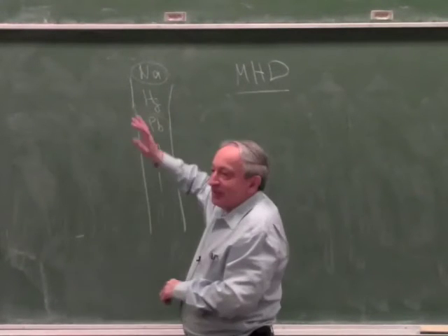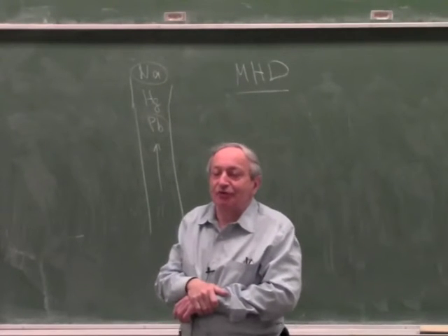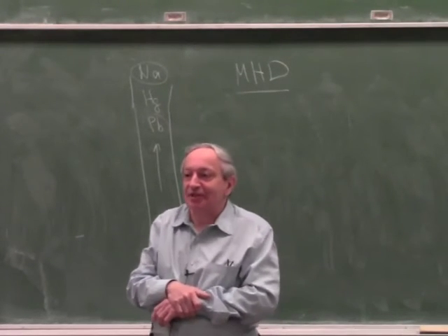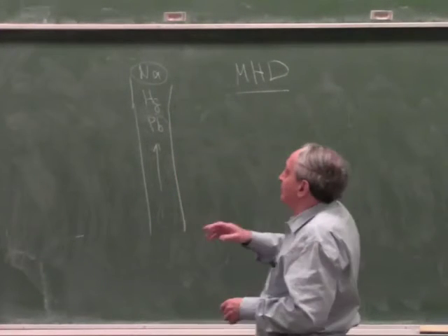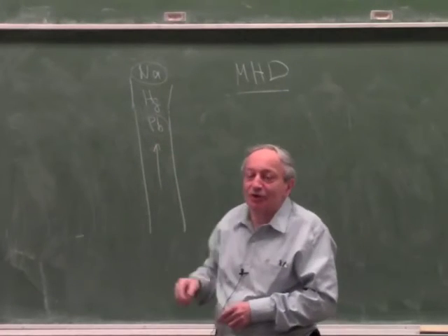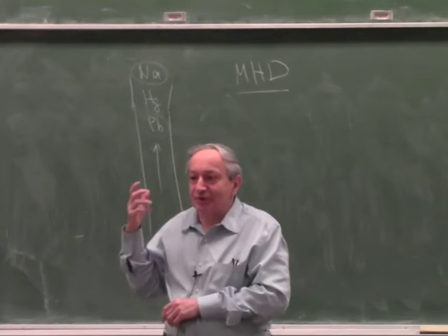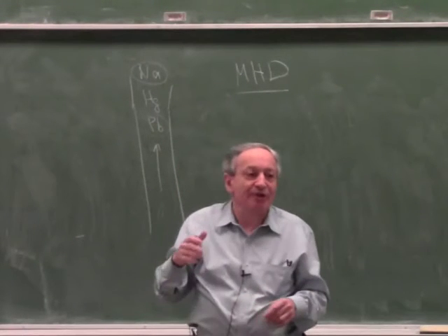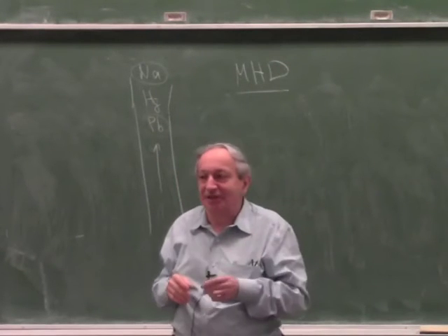Sodium melts around 100 degrees, so there are lots of applications that actually want the fluid to be liquid metal instead of water, and it has all kinds of advantages. I won't get into it. So anyway, mercury today is used less, but there are some systems which use mercury as a working fluid. The early nuclear stations, some of them used mercury as a working fluid, again because it boils at a much higher point than water, so you don't need high pressures to transfer the heat.